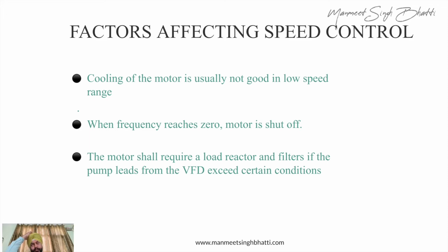So that is a very important factor that you should consider whenever you are using a VFD with a motor. Be sure how low you can get the RPM. If your RPM is 20 to 30% of the actual rated speed, it is better to put in an extra fan for the cooling of that motor.